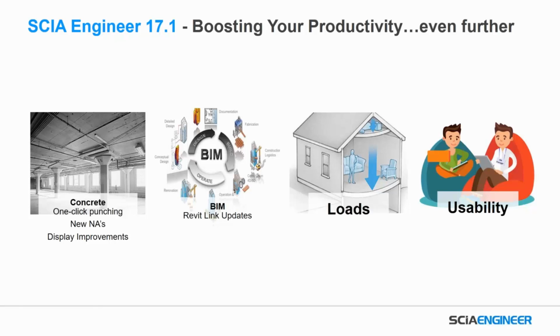That was a big improvement this release, and so with all the information for composites and joists and different things, all that information now to really complete that composite workflow was added in this Revit link. Loads, we extended the tributary area to include openings. That was a big thing that we needed to do to make sure that those calculations were done right and the vast majority of slabs could be accepted. We could use tributary area on those types of slabs and decks.